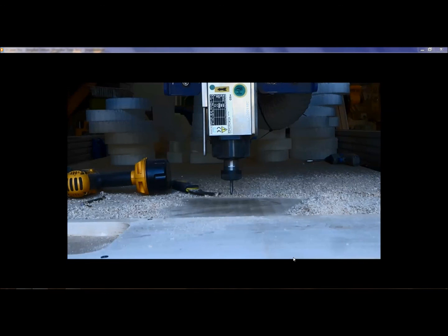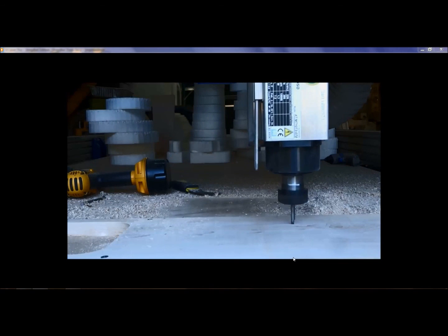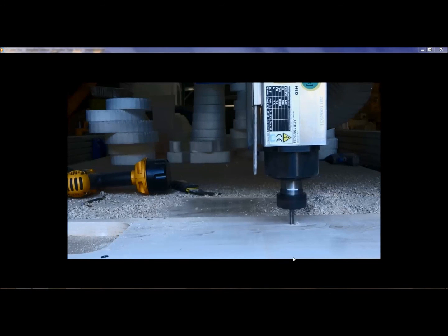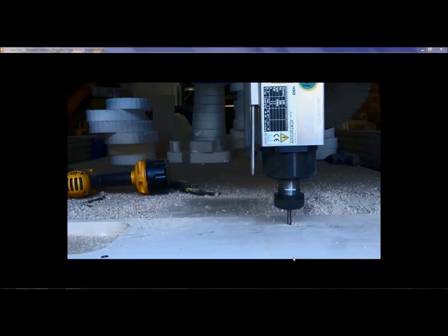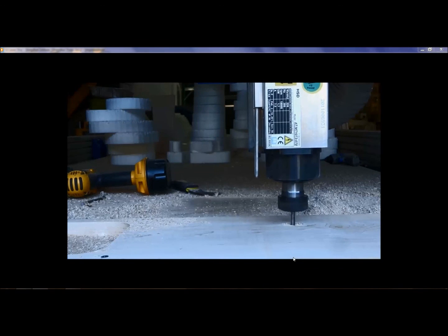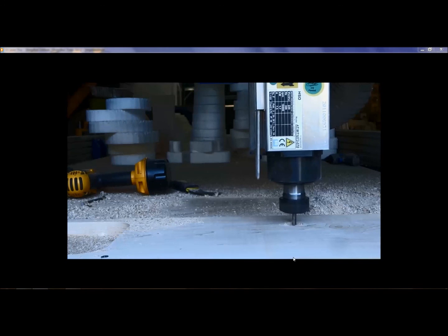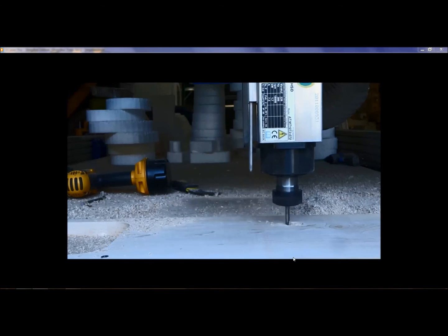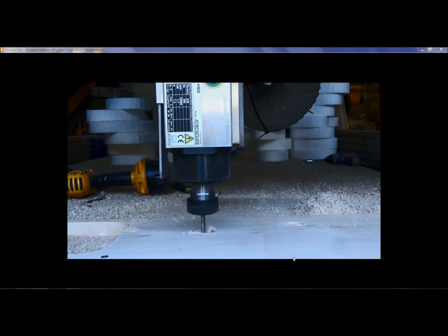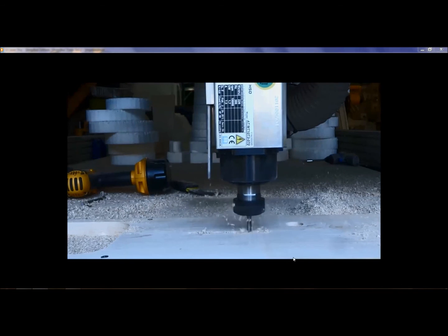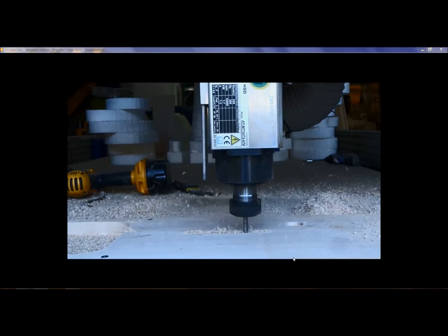And just to show you up close, what these ramps really are: here was the zigzag ramp, where it's zigzagging back and forth, and this is on a circle, so it zigzags around a circle, gets to that depth, goes around and cleans it out. It zigzags back down to the next depth, and then goes back and cleans that all around. So it'll always clean out the previous ramp. And then here's a longer one, where it ramps back and forth, comes back, cleans out the ramp, and then goes ahead and finishes the pocket at that pass depth.